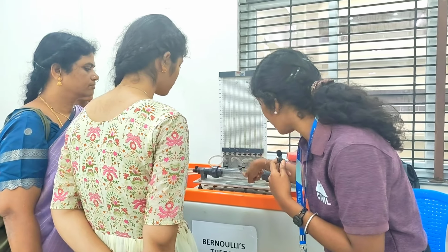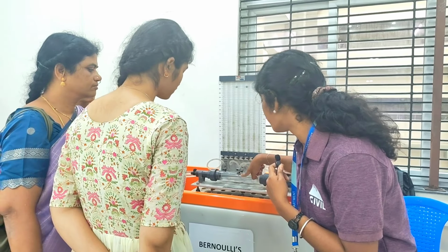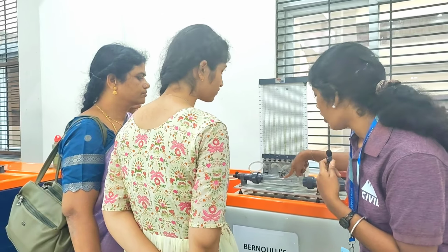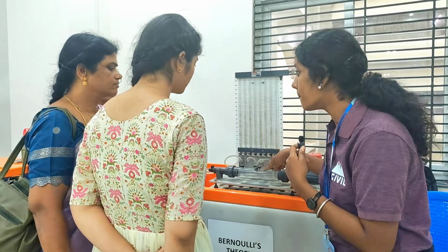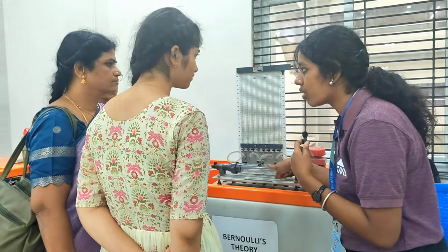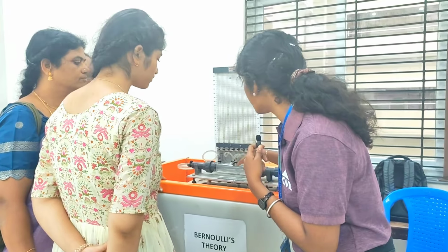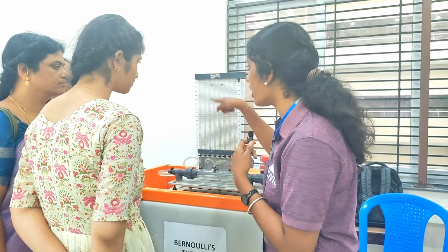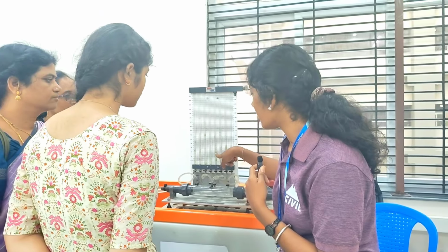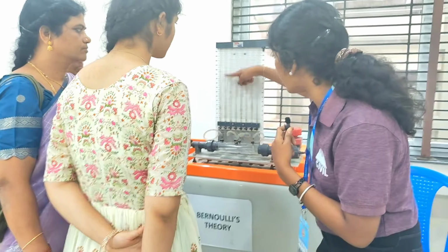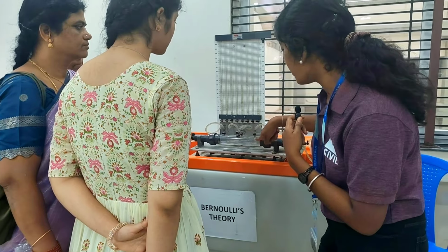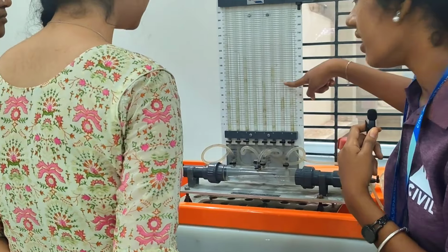Coming to this constricted area, the area is very less here, so the velocity will be more here. Since the velocity is more, the kinetic energy will be more. Kinetic energy is more, so the pressure energy has to be reduced so that the total remains constant. You can see as the area decreases, it has reduced gradually. Then again, coming to this divergent part, it increases again.